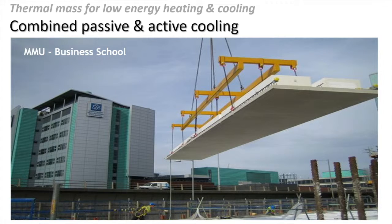And there's one of the units at the Manchester University Business School being craned into position. These are about 12 metres long, 475 millimetres deep, so they're quite deep, but they've got void formers made from polystyrene to reduce the amount of in situ concrete that goes on top of these units. So it's a combination of in situ and precast.